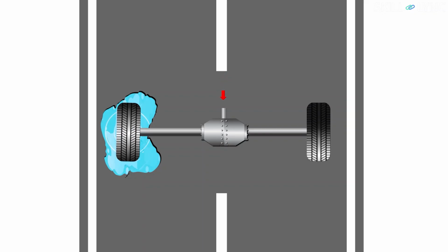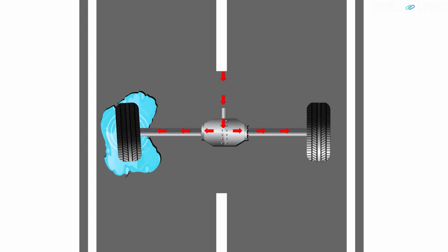A good example for this is when the wheels are in slippery conditions like being stuck in mud. When any one of the driving wheels slips or goes off-road, it spins faster than the other. At that time, the slipping wheel limits the torque because of less traction. When this limited torque gets applied to both the wheels, the vehicle cannot be moved much. In order to move the vehicle, more torque should be applied to the non-slipping wheel than the slipping wheel.